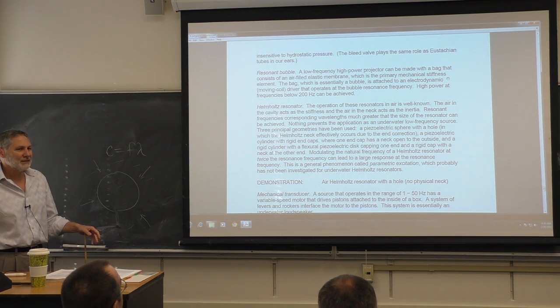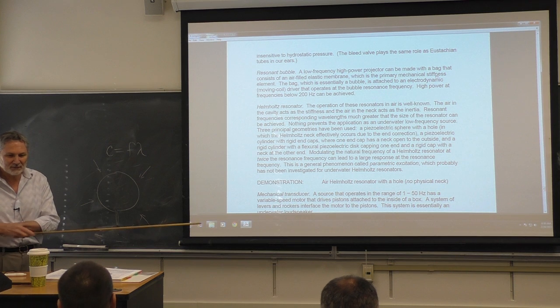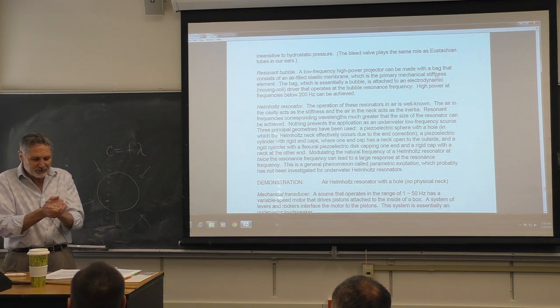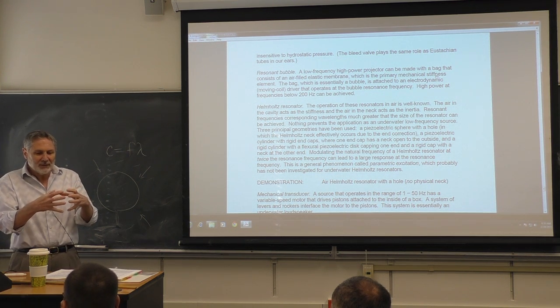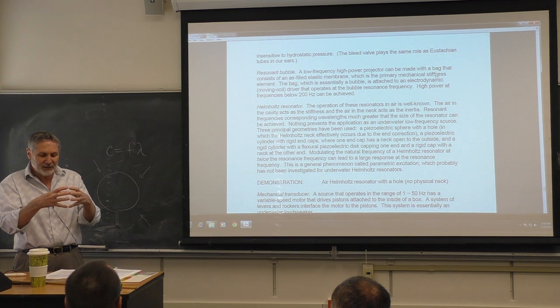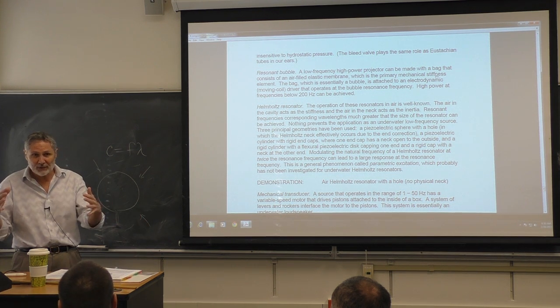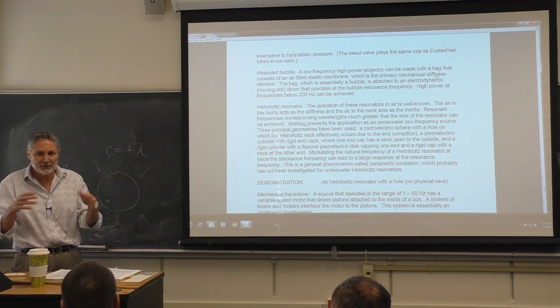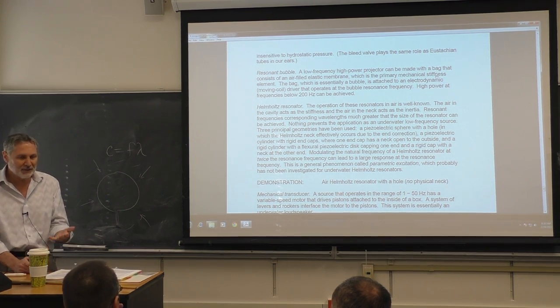And let's not forget, remember Helmholtz resonators? The basic idea of a Helmholtz resonator is you've got a resonator that has a certain size and it's resonating at a wavelength, the wavelength for resonance, that is much bigger than the size of the system. So it's not a typical standing wave resonance. It's different. It's a Helmholtz resonance.